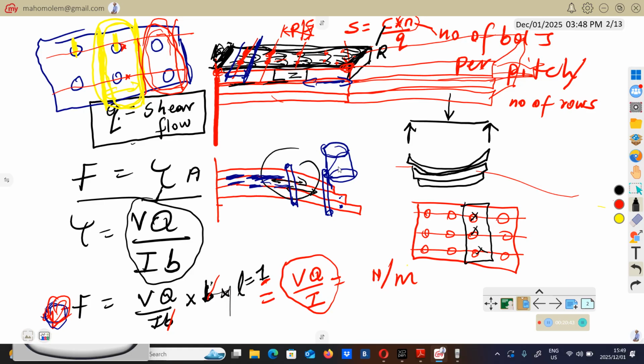So remember here I said that we don't want to see this sliding here. We don't want our material to slide over each other. So to prevent that sliding, it means that we have to put the fasteners, let's say the bolt. So if you put the bolt here like this, as this thing starts to bend, the material will be pushing like this. We'll try to push this bolt like this. And then this bolt has to resist.